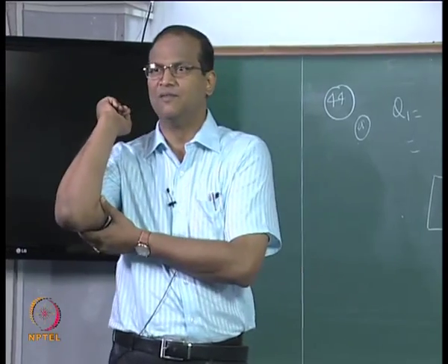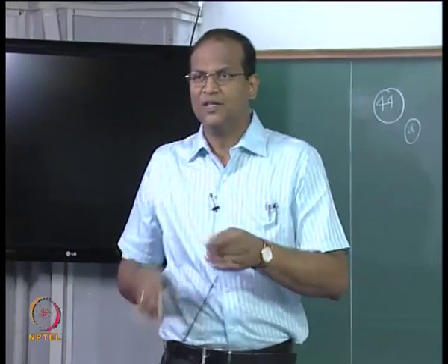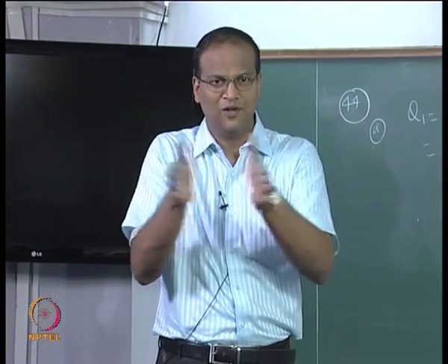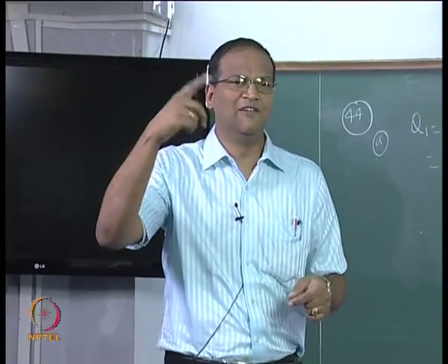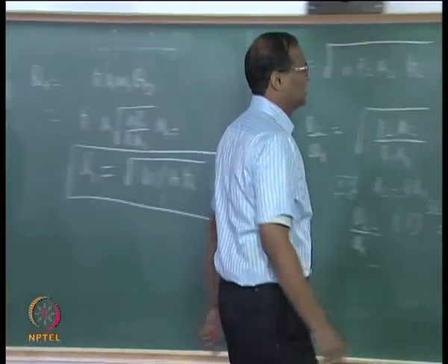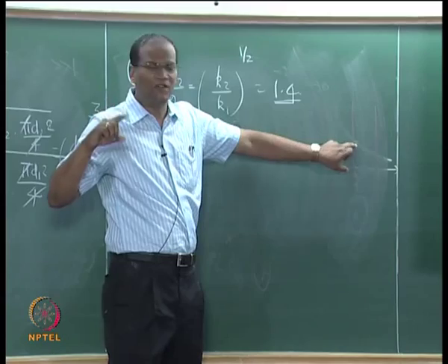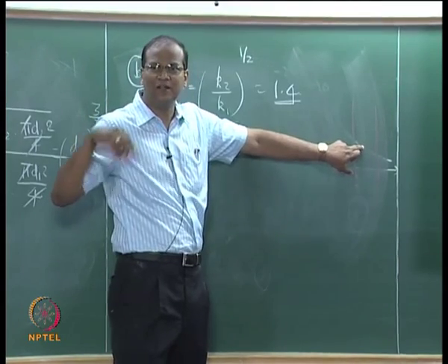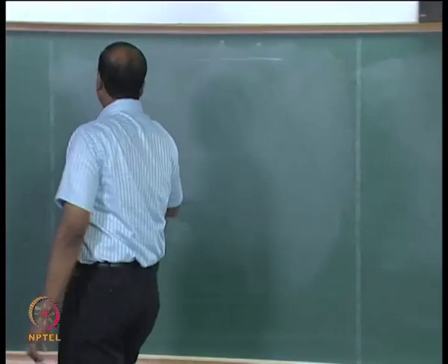So you can do some additional work. I don't normally do a problem like this, I do not have time now. That is, you have a fin set up and measure some temperatures, then you keep on guessing the value of thermal conductivity, it will give a theta versus x curve like this for various values of k. There will be only one value of k which gives a curve which is closest to the experiment, and that curve should be the best representation of the thermal conductivity. So that is basically what is called an inverse problem. Now we will go to